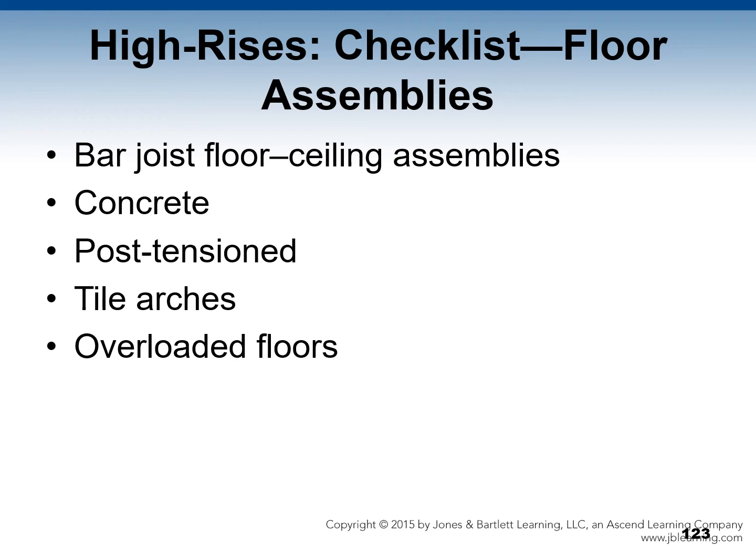Continuing on that checklist, you need to talk about floor assemblies. If it's a bar joist floor to ceiling assembly, what is the integrity of the floor? Also, what needs to be considered is concrete. Are the floors of solid reinforced construction or composite decks? Post-tensioned floors should not be drilled or cut, but they may have drill holes or cuts in them. Tile arches are dangerous to cut because the entire panel may collapse.